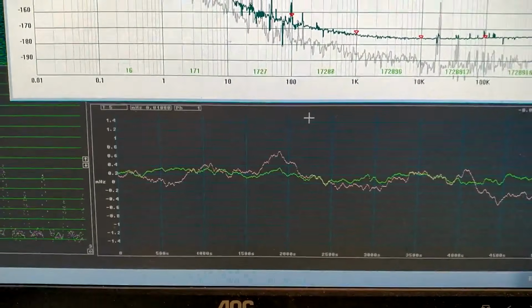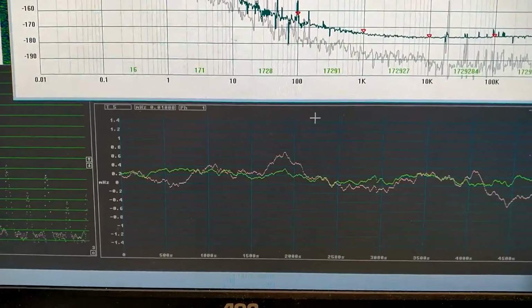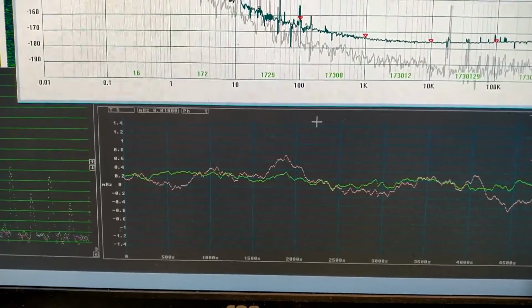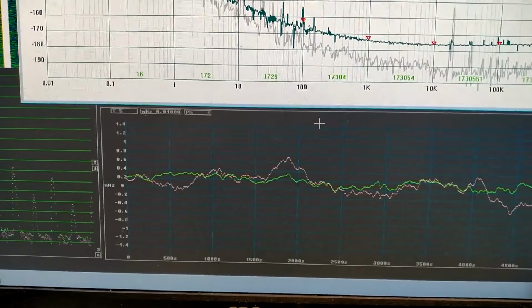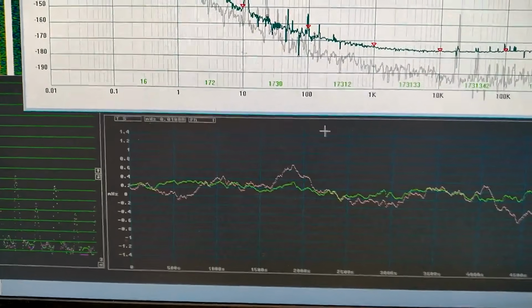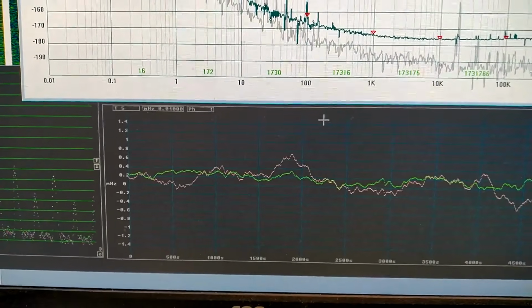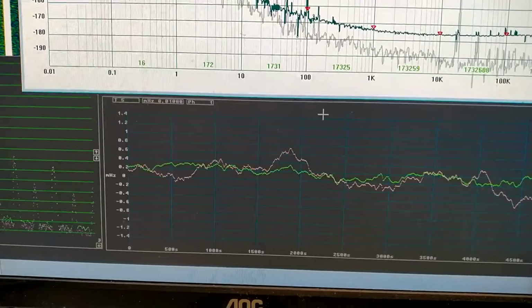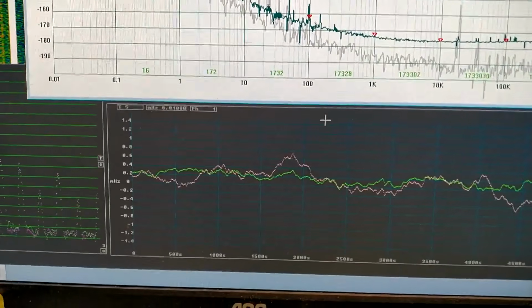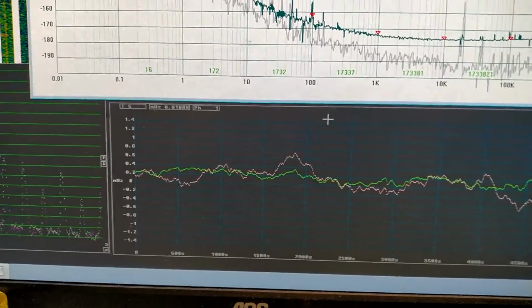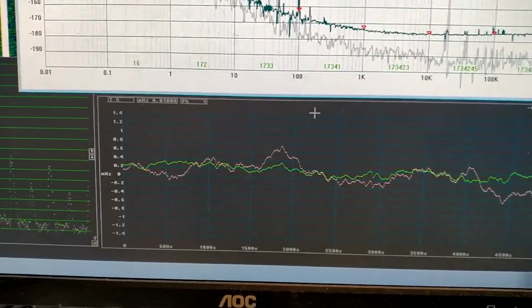The green trace, the frequency versus time for the Wenzel oscillator, is a combination of the noise from my 4-crystal oscillator and the Wenzel oscillator. The red trace is my channel 2 oscillator, which is phase locked to the Wenzel.